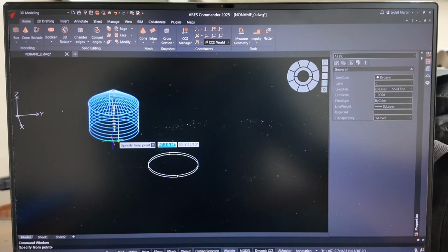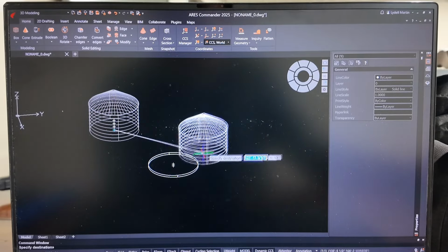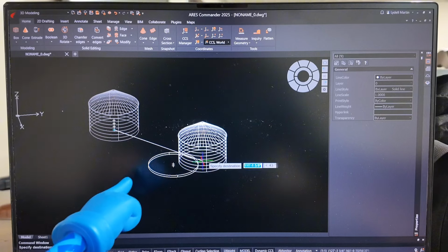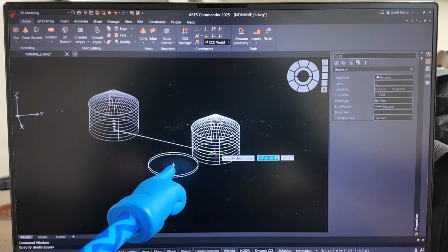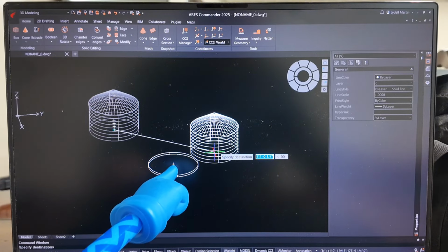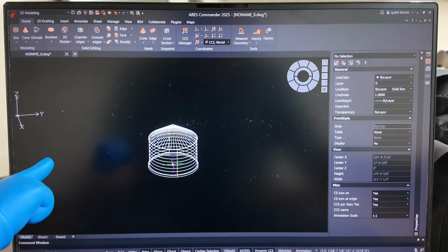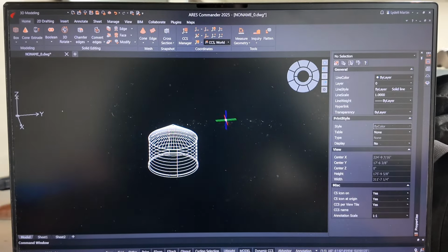I'm going to go in here and we're going to find the center of the bottom ring. Left click on there, and now we find our pointer goes across that ring, it shows us our 2 X's. We want to line our pointer up with the top X so it's on top of the concrete. Left click there.